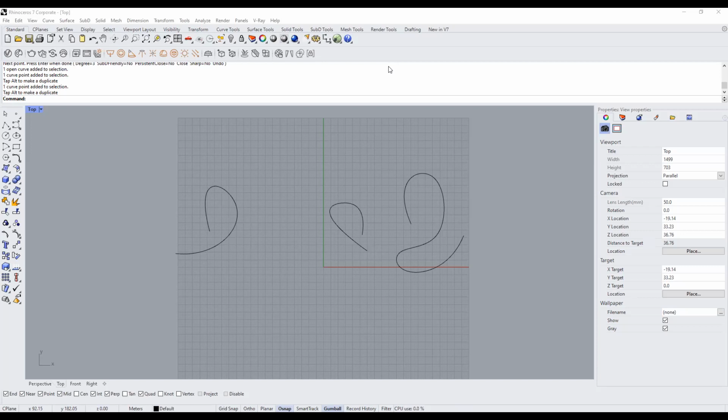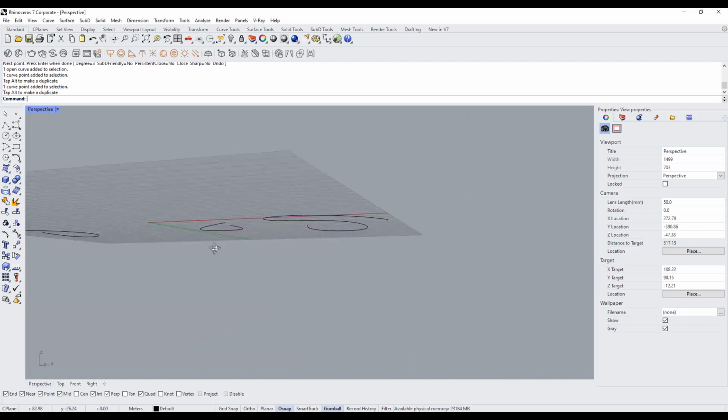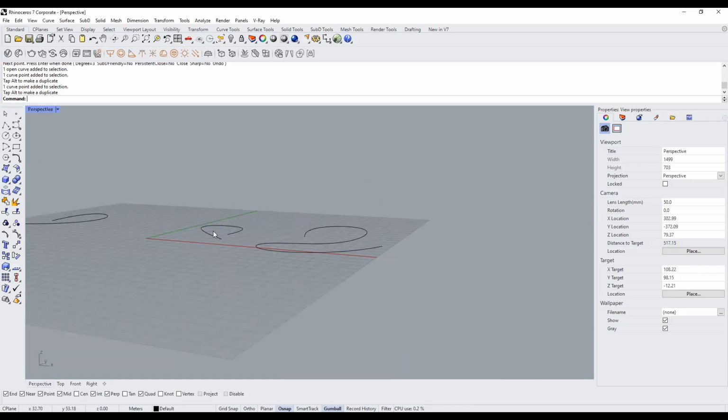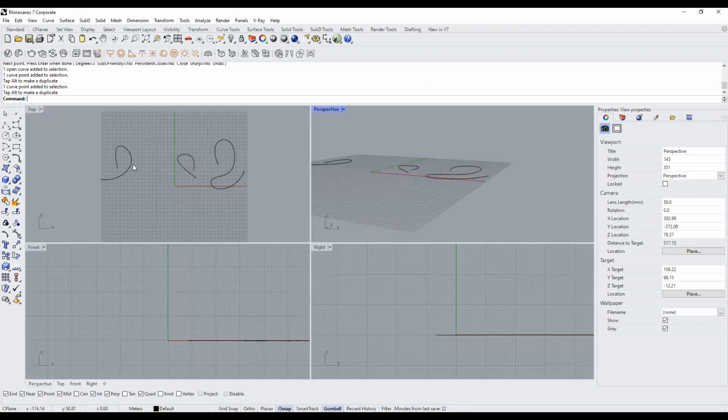compared to Revit. And to again answer your question, you do not have the concept of levels in RHINO like how it is in Revit. You just work at different heights in perspective to get that result. How to make sure your model is drawn in one level? When you're working in the top viewport, it's automatically going to be in one level.